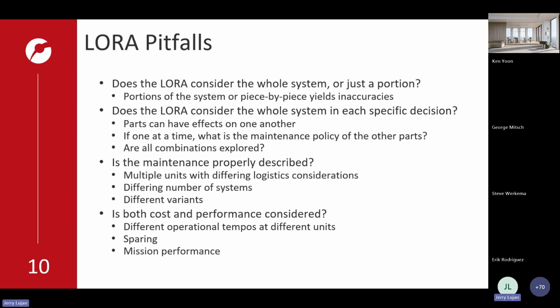Now let's say for a moment that we are considering a LORA and we have some kind of sunk cost that we have to consider. Let's say it's $45,000, and we're doing a LORA on a starter, a generator, and an alternator. Okay, 3 items that are all standard copper wound motors, so they need the same test bench and equipment to be able to repair. And there's a $45,000 setup cost.